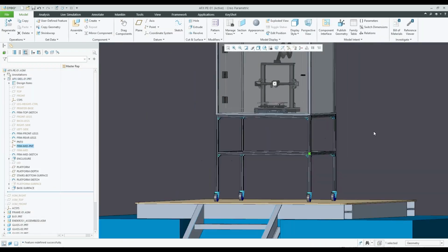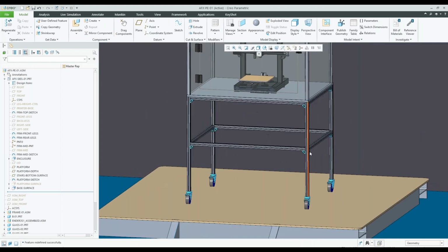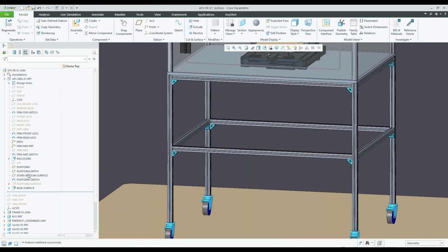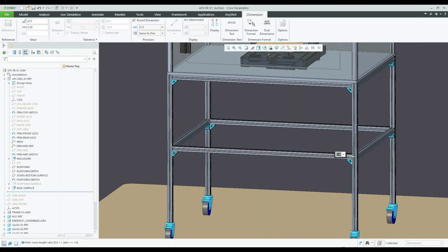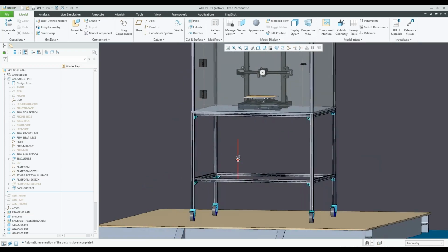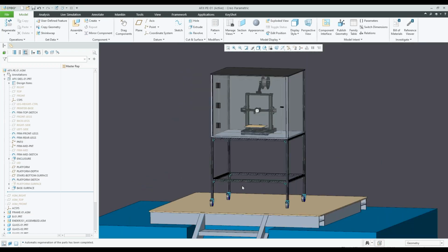And then I basically created a datum plane on that point parallel to the top plane. So now if I want to control the position of that mid support, I can take that point, edit definition, this one here, edit dimension. I can say, you know what, let's make this a little bit lower and change this to 0.7 or something, regenerate, and now it's moved lower. Okay, pretty powerful stuff.